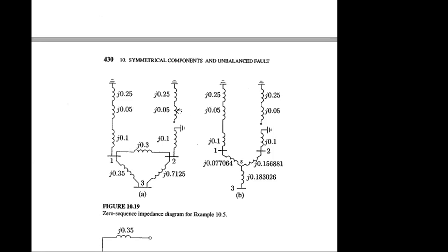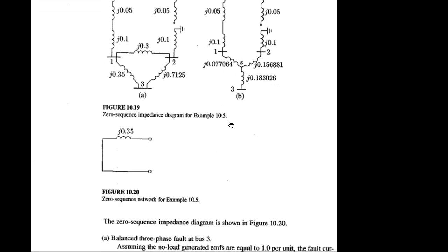this part, regarding that part, that is actually not required for the zero sequence circuit. Is it there in the connection? This connection is completed through that ground, right? So you have to consider up to this point. This part will be cancelled, or this part is not required for the equivalent circuit or equivalent impedance calculation. So after calculation, you can get the zero sequence impedance as 0.35.